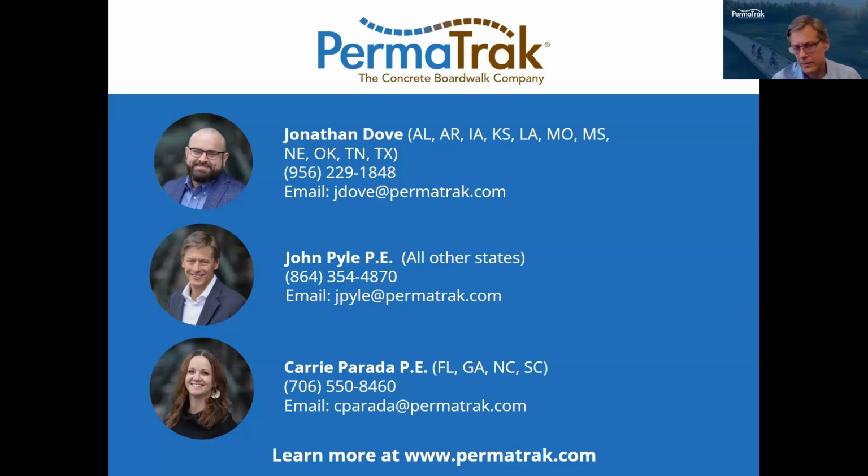I will try to take the river question first. So this is a tidal river. Part of the issue there would be the waterway: understanding the water flow and the velocities of the flow. That's going to impact your foundation design as well as the structure design, because the moving water is going to impart a lateral load, as Jason had mentioned.